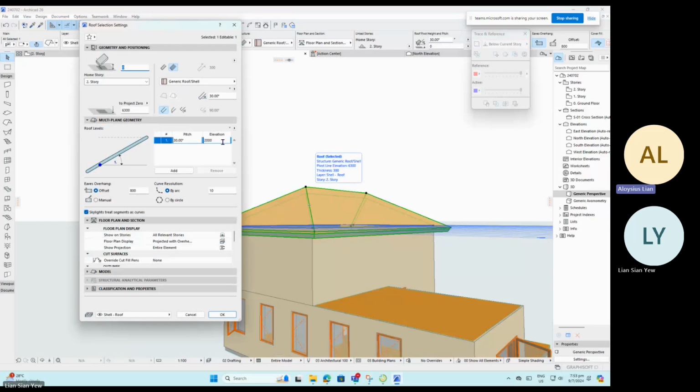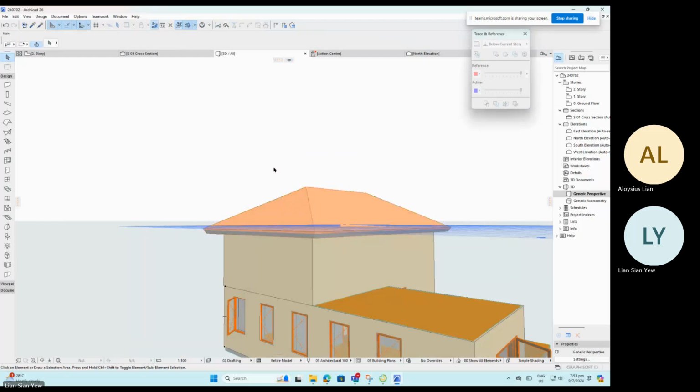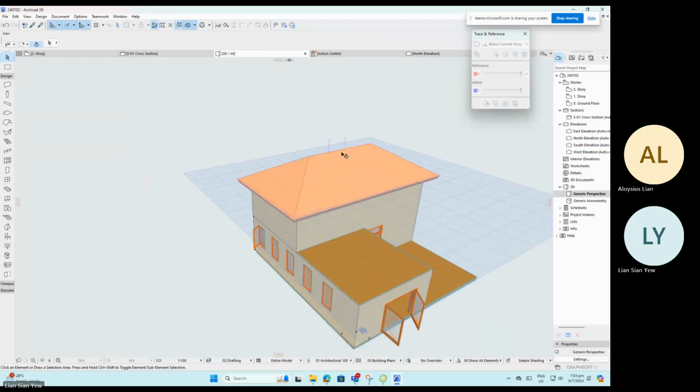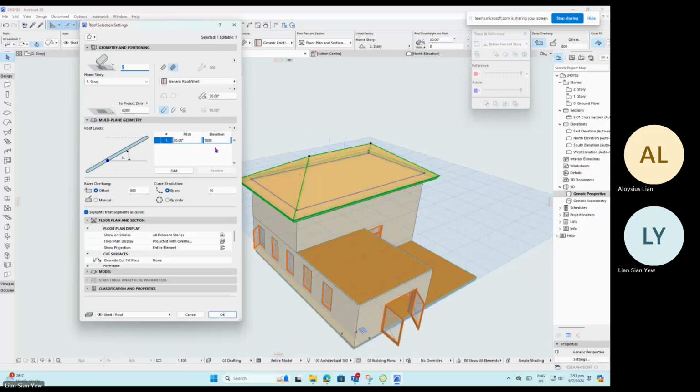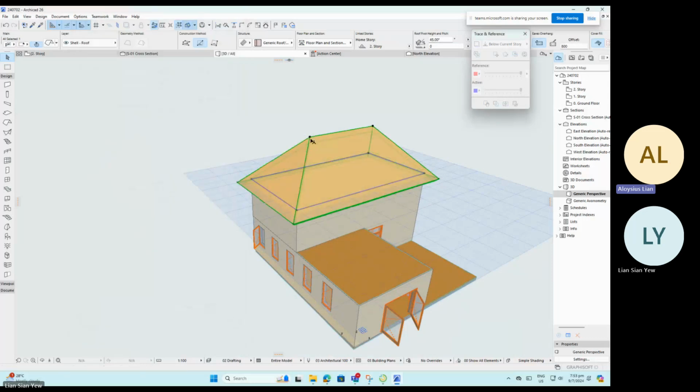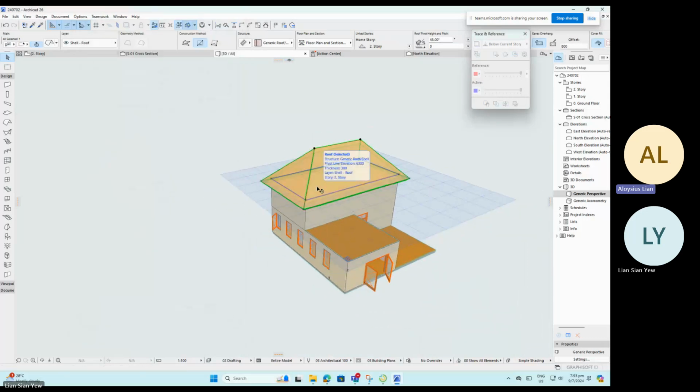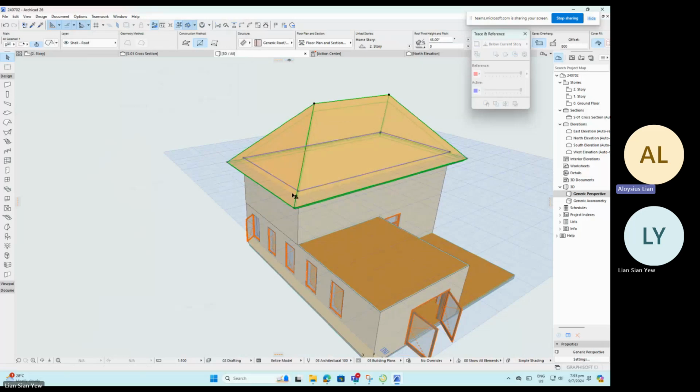Control T again. I can change this elevation. So the elevation means the tip of the point. If I change this now to 1000 and I click somewhere else and click OK, see, the height will be adjusted. I can also adjust this to 45 degrees, but yet with a 1000 elevation. What it does is that it will know that and calculate from the projection that you have as of this blue color rectangle, right?